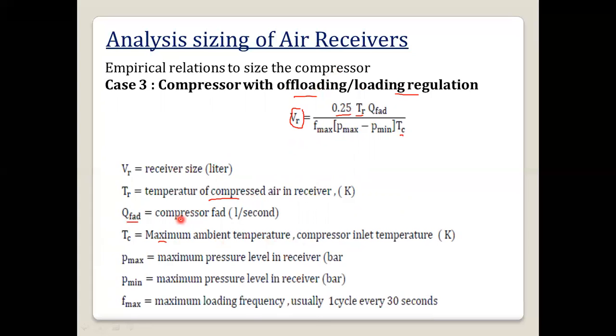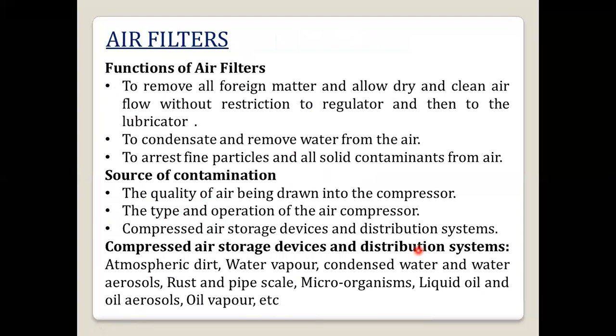QFAD is the compressor free air delivery, in liters per second. P max is the maximum pressure level and P minimum is the minimum pressure level, here in bar. F max is the loading frequency, usually one cycle every 30 seconds. So this was about the air receiver.